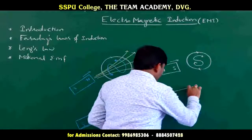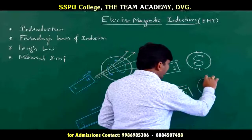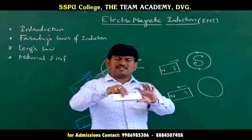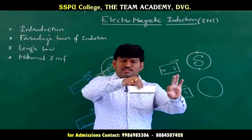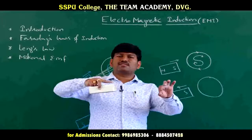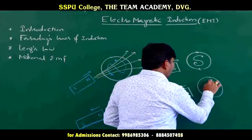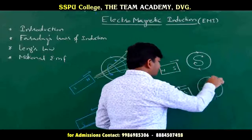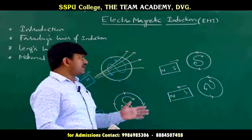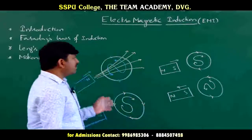And next example, if this is south and this is north and this is going like this. Now in this case, what is the direction of induced current? Here this is south and this is north. South is moving away. When it is going away, it should be attracted. Attracted means south is attracted by which pole? North pole. So just draw north and keep arrows at the tip. So what direction are you getting? Anti-clockwise. Is it clear or not? In this way, we can get the directions for induced current simply using the Lenz law.